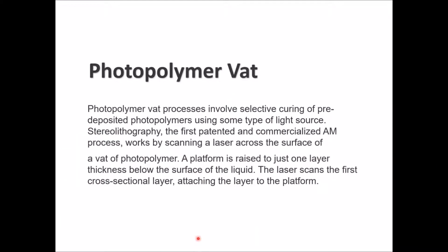The photopolymer vat process basically involves selective curing of pre-deposited photopolymers. It basically uses some type of light source. For stereolithography, the first patented and commercialized additive manufacturing process, it worked by scanning a laser across the surface of a vat of photopolymer. The platform is raised to one layer of thickness below the surface of the liquid. Then the laser scans the first cross-sectional layer, attaching the layer to the platform, and so on.